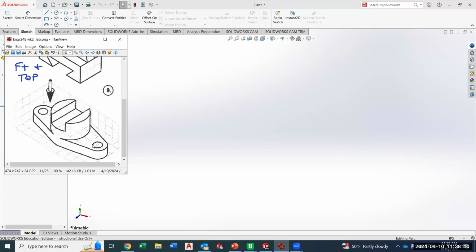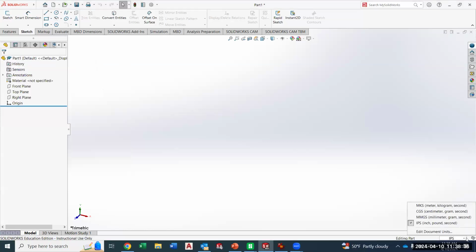This looks like a 10 millimeter diameter hole, right? Because there are 10 millimeters for every grid, and that looks like one grid spot. So 1, 2, 3, 4, 5, 6, 7, 8, 9, maybe 10. Yeah, I guess I'll say 10 on the full. So 100 millimeters on the full, right? Remember, that's down here in this corner. We want millimeters, so we want to switch that right away.